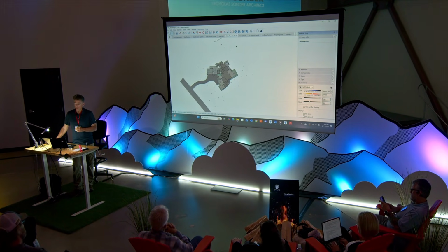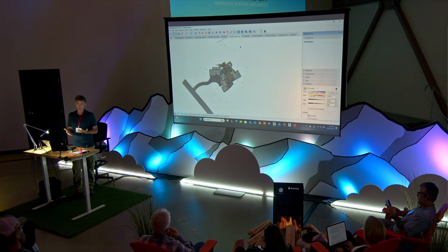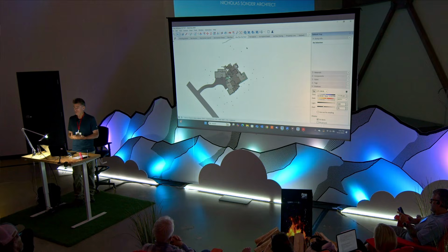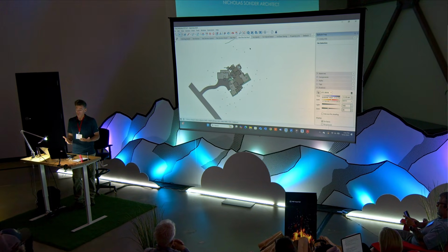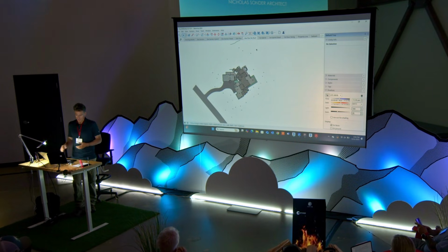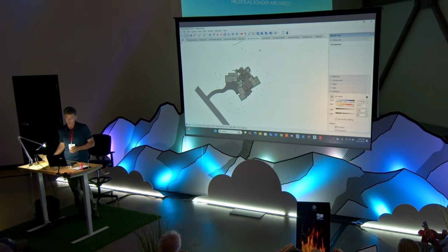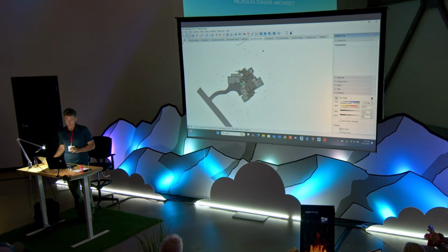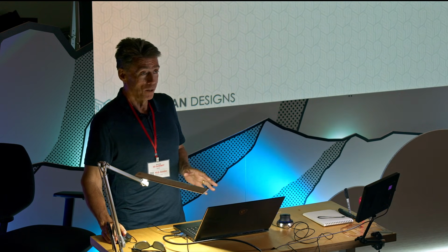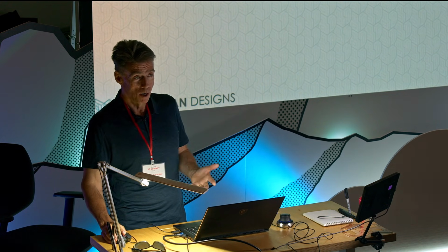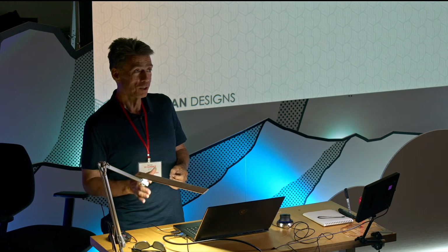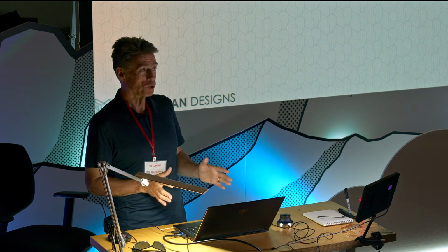This is because I do different site plans to tell different information. The site plan with the roof on I use for the construction management plan. With the roof off is used for things like the landscape plan, any grading, or best management practices, things like that. And so that is really the key, is organization of your model to keep it efficient. Watching your level of detail is probably the most important thing.